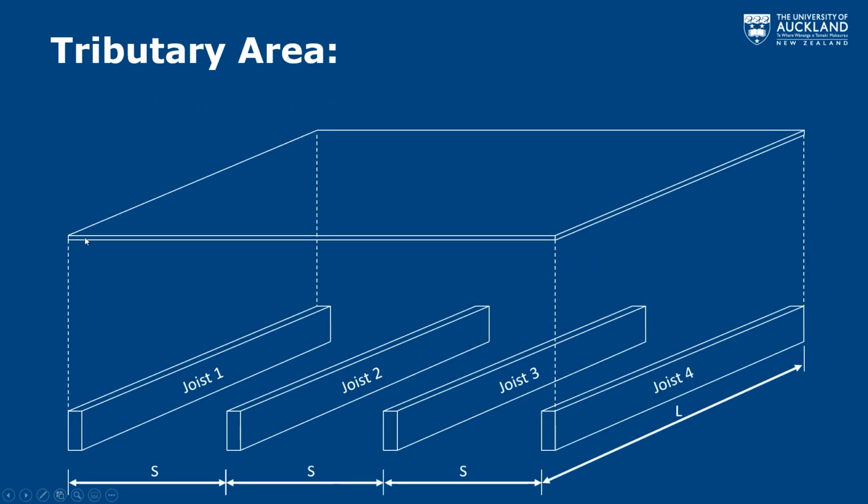So, if we think about our slab, or our piece of plywood here, as our simply supported beam, and you could be looking in this direction, you could see that you've got a reaction here, reaction here, reaction here, reaction here. Well, the first thing that you would say is that this is not simply supported. It's got 1, 2, 3, 4 reactions. And this is one of the simplifying techniques that we have to do, is that we will treat the distance between the joists as its own simple beam.